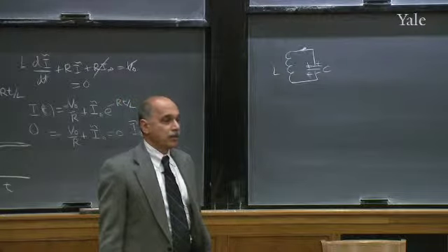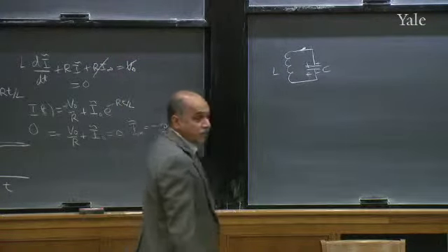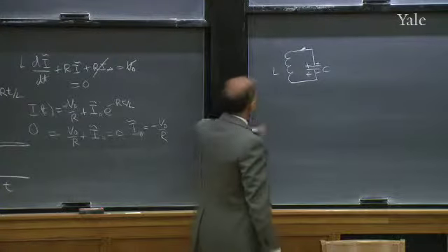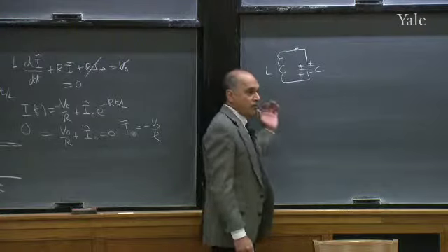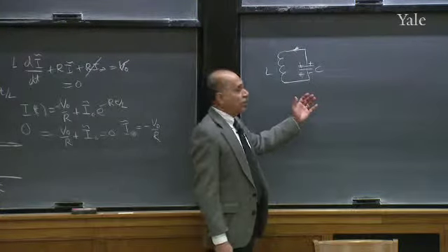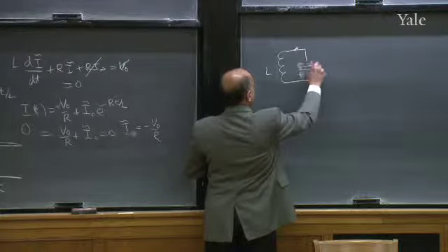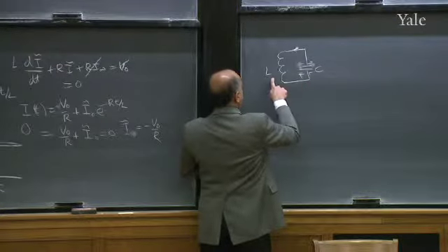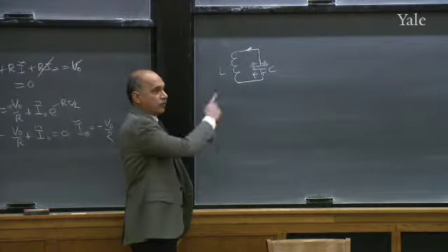Yep. Kind of like the inductor has momentum and it keeps pulling. The inductor would have had a current by then. So the inductor is not going to suddenly stop having its current. So it's going to keep driving more current for a while until the capacitor is charged up the opposite way to an extent that this fights that voltage, and then it'll go the other way. So it'll go back and forth.